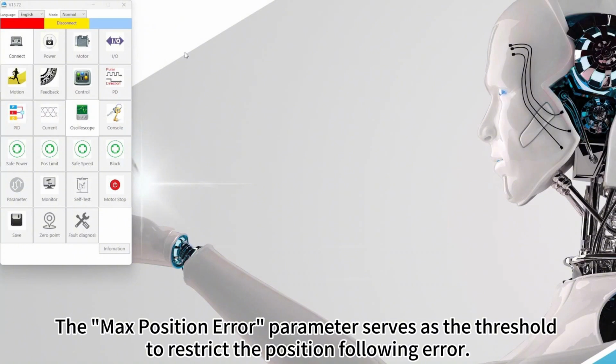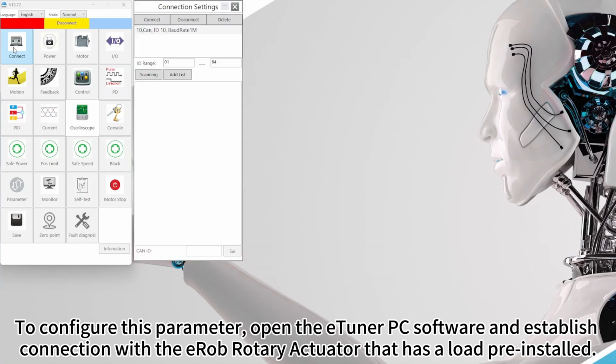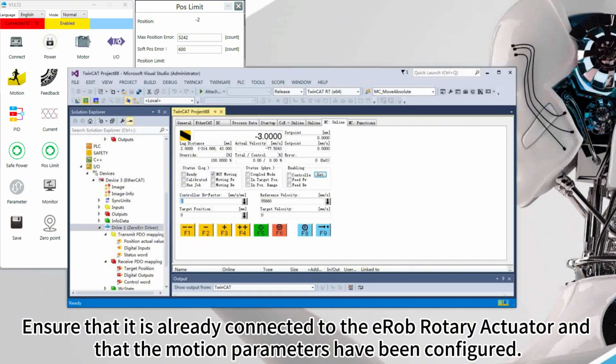The maximum position error parameter serves as the threshold to restrict the position following error. To configure this parameter, open the eTuner PC software and establish connection with the eRob Rotary Actuator that has a load pre-installed. Navigate to the position limit menu, where you will find the settings for the maximum position error at the top. Next, launch the TwinCAT software. Ensure that it is already connected to the eRob Rotary Actuator and that the motion parameters have been configured.